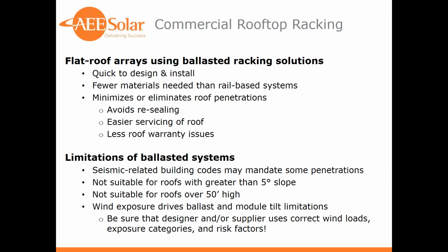Some considerations when you're considering a ballasted system though, in states like California that have seismic concerns, they may mandate penetrations for seismic anchors. These are generally at the corners of the PV arrays to keep the array from moving around. So most of the array is supported by ballasting, but seismic anchors may not be avoided in certain areas.